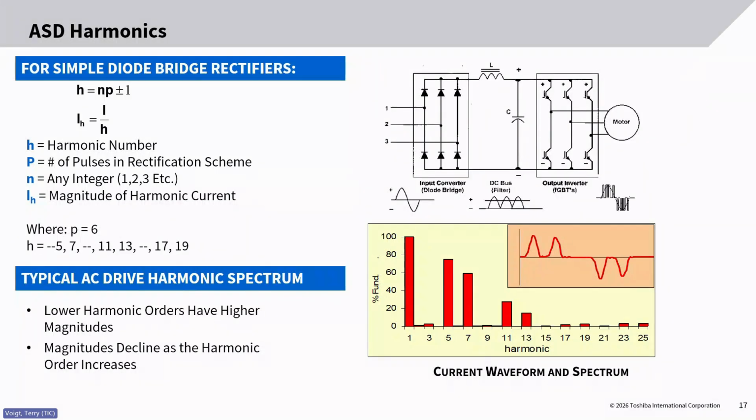Those diodes block voltage in one direction and allow voltage in the forward biasing direction, right? So during that negative biasing, that's highly influencing the amperage, and then also the resulting voltage comes into play as well. So that's ultimately why it's being generated, but which harmonics are being generated?